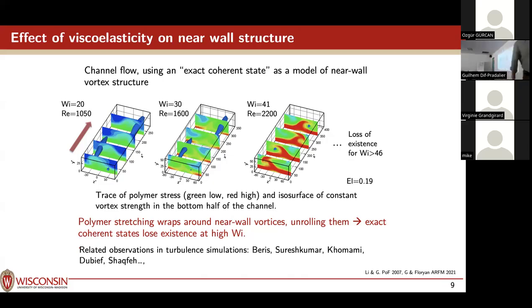Yeah. Probably depends on concentration, but do you need to consider compressibility? Yeah, so here Mach numbers are very low. We're considering these to be incompressible flow, even with the polymer. That's right. The polymers are present in very small quantities. Even for polymer melts where there's no solvent at all, incompressibility is a very good approximation. So in this case, we can assume incompressibility.